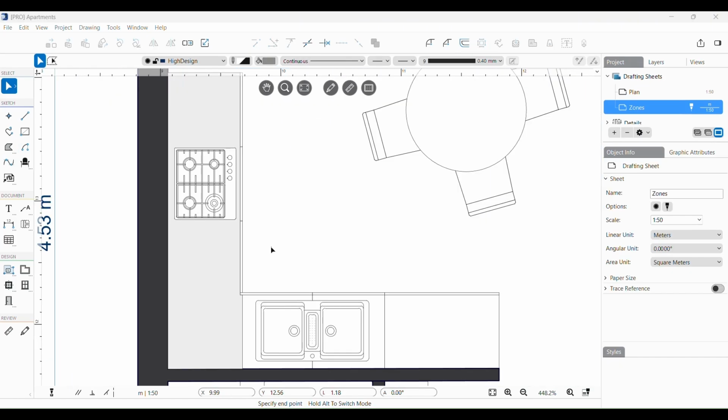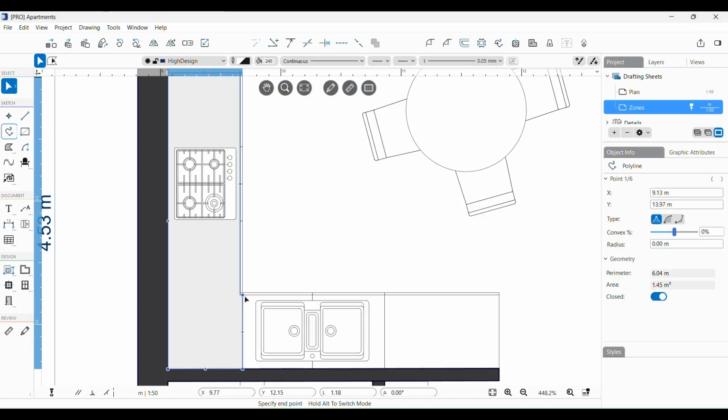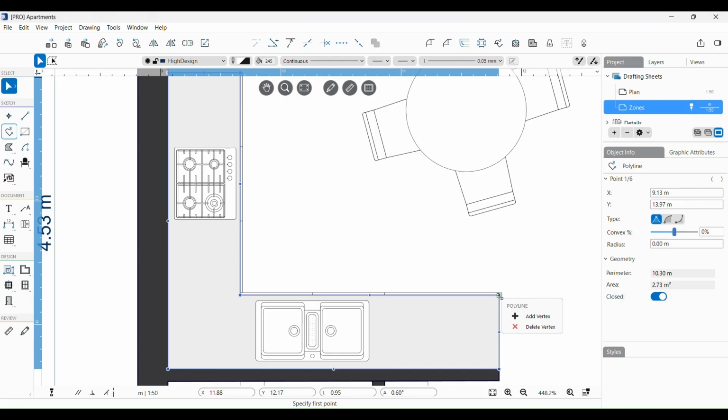Objects that don't have a center: polylines, hatches, and fills, curves. Click a vertex and move to reposition it and change the shape. Click again to confirm. Click a midpoint of polylines to move the straight segment and consequently stretch the contiguous segments. Click to confirm. Clicking the outline of hatches and fills and curves will add a new vertex. Hovering the cursor on a vertex of a selected hatch, polyline, or curve opens the pop-up menu with the options to edit the vertex or change the outline.